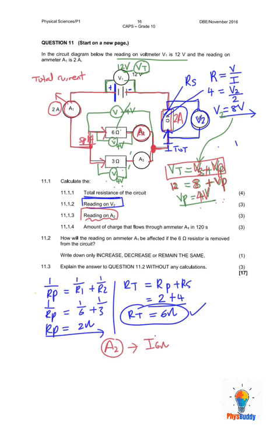So I 6 ohm, current in the 6 ohm. If I use R is equal to V over I, the resistance is 6. The voltage we calculated across parallel was 4. And this would allow me now to find the current. That gives me 4 over 6 or 2 over 3, which is 0.67 amperes. And that is the current in ammeter A2.